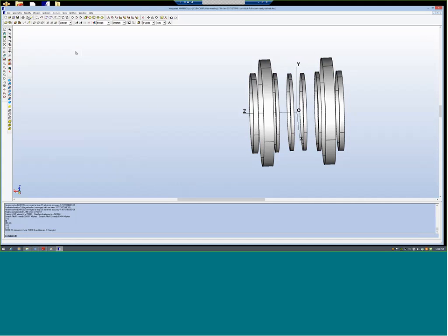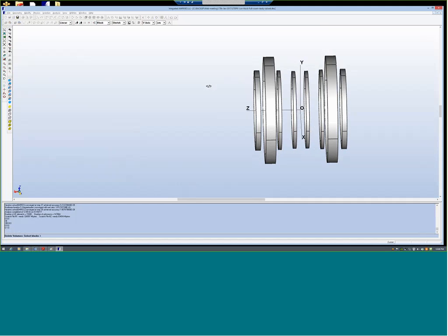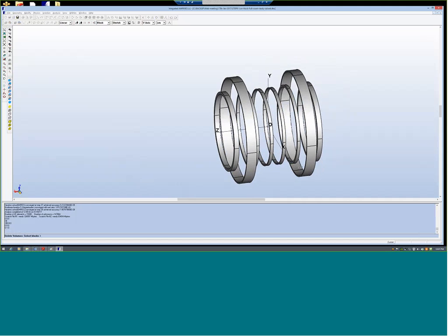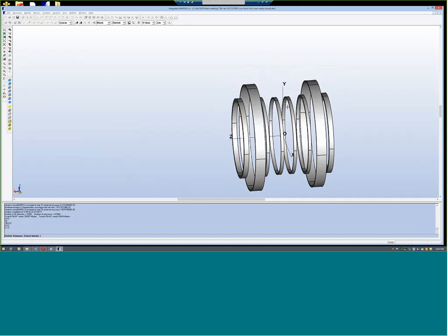Okay, now modify, delete. When you are applying a symmetric condition, suppose now I want to apply a symmetric condition at the z equals 0 plane, that is the xy plane, then I'm allowed to model the problem only for z greater than or equal to 0.